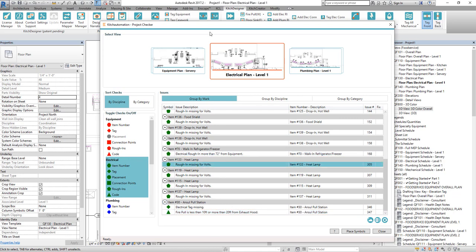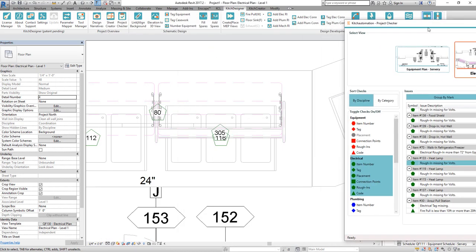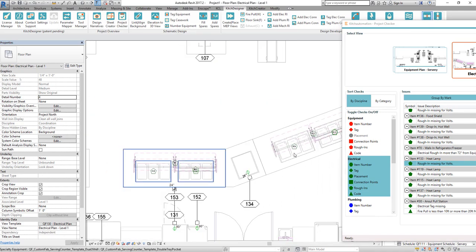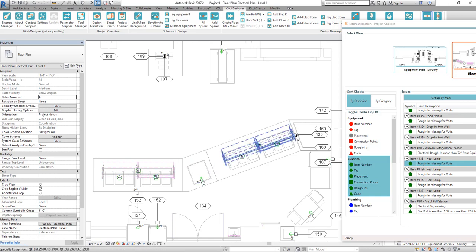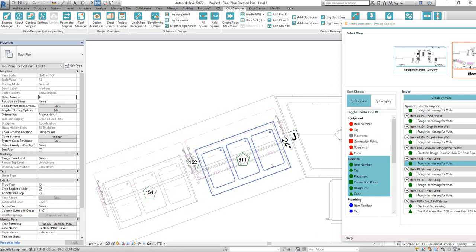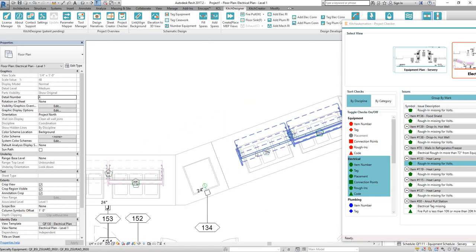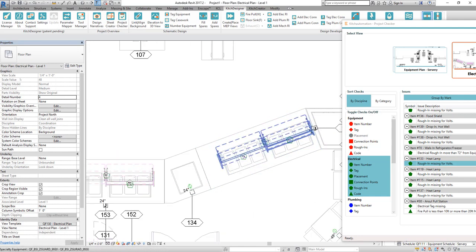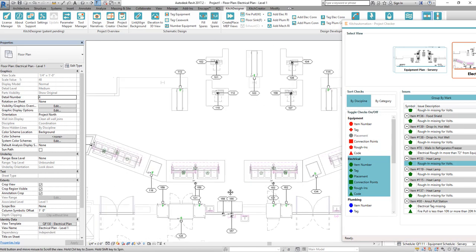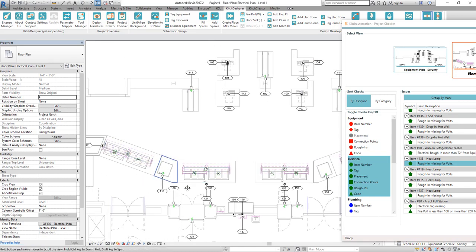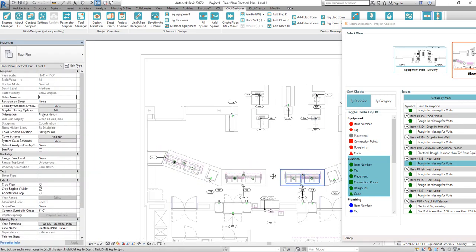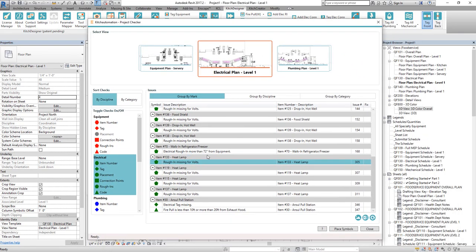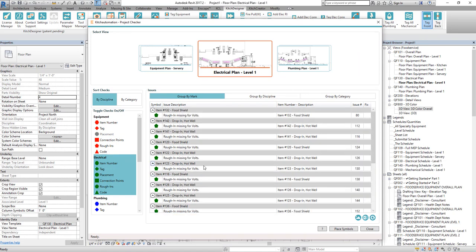All these rough-ins that are missing, let's double click those, and I actually know what they are. They're all the drop-ins and food shields on these counters, and the reason for that is this project had sub-panels, so these counters had single-point connections, and all of the electricity came from one point over here, and so they actually don't get rough-ins because there's this single-point connection. And so the walk-in we kind of went through, so that's electrical.